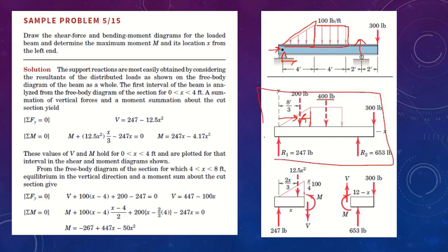But now we have to develop formulae for the far left hand element for shear force and moment. Now for shear force, at this point, pin joint 1, we have 247 pound force as a reaction R1, and just immediately to the right at a distance x, let's say, you have a shear force V and a moment acting on it.